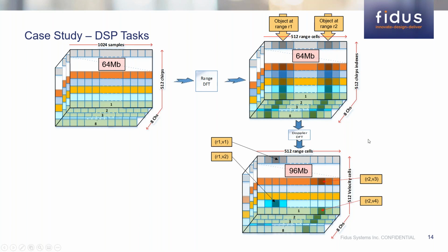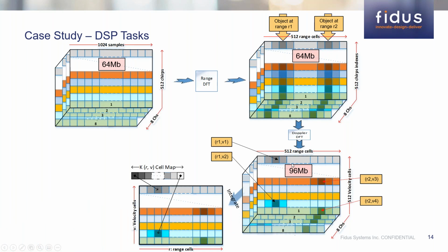In parallel, we are going to do another operation, which is integration. It consists of accumulating the energy, the power, across the channels, and keeping a programmable number of entries in a given order, descendant or ascendant, it doesn't really matter. And we are going to feed the Doppler cube and this list to a proprietary CFAR algorithm running on the PS to finalize the detection.